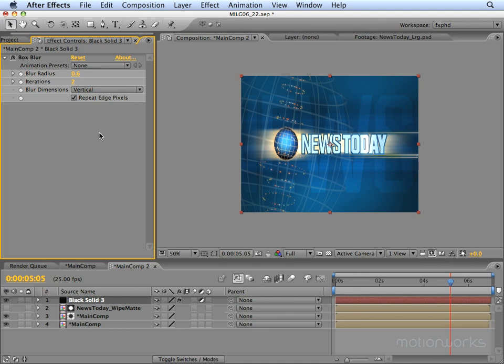And what can happen on occasions, for instance, is if you have a really saturated bright colour, the frequency range of that colour when it's being broadcast will move into the frequency range of the audio, and this can cause problems with the audio such as hissing and things like that.